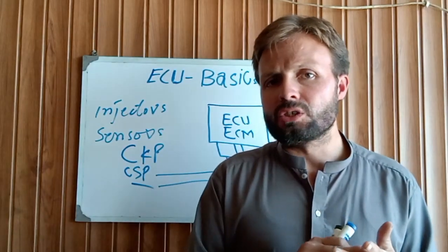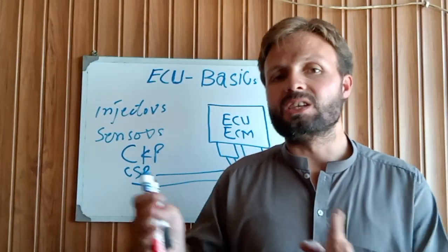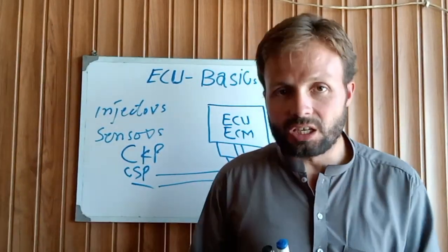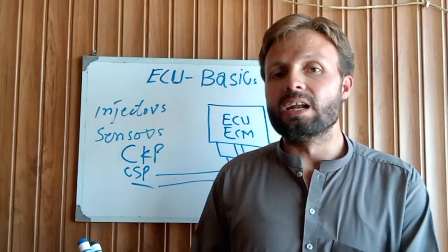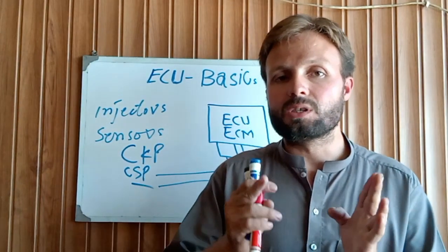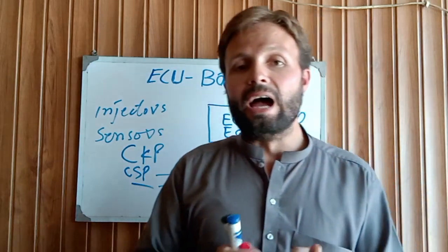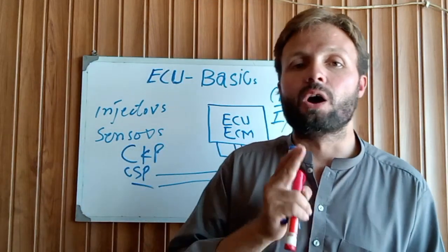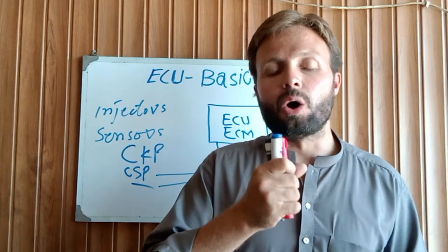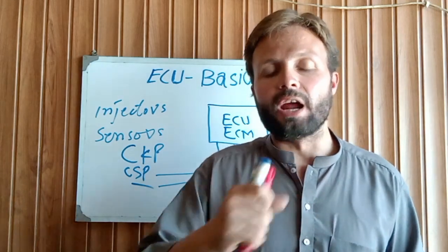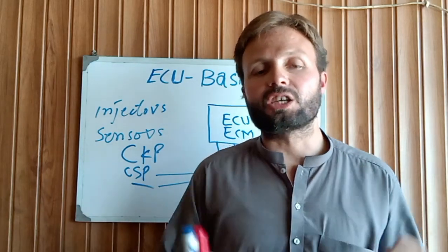Also, the camshaft position sensor activates all the injector pulses, giving a signal back to the ECM. The engine is rotating, and the ECM figures out which piston is at top dead center and sends the pulse to that injector. In this condition the piston goes to combustion, the piston goes down and rotates the crankshaft with torque force, and this torque is converted to